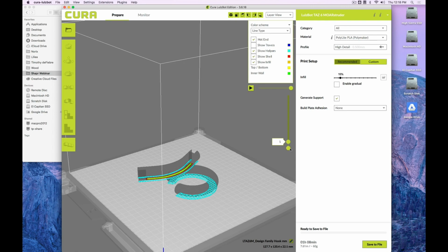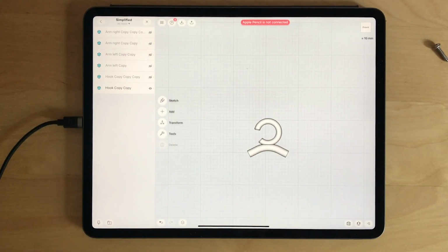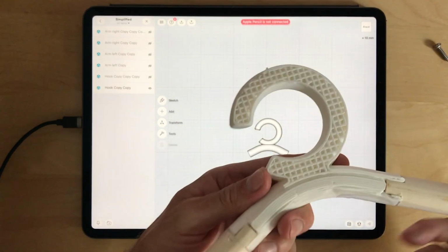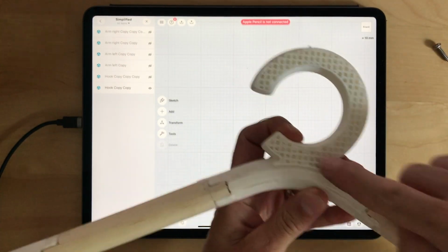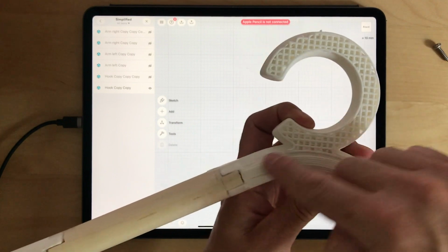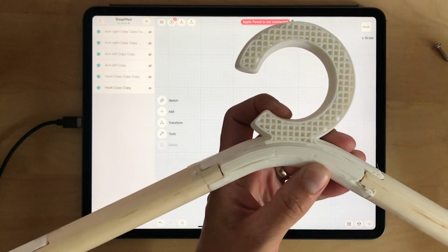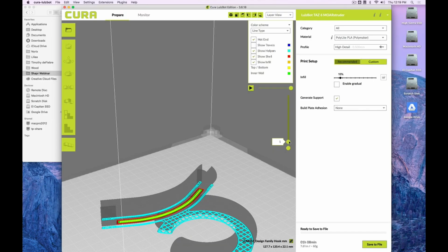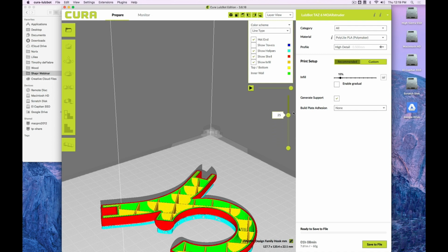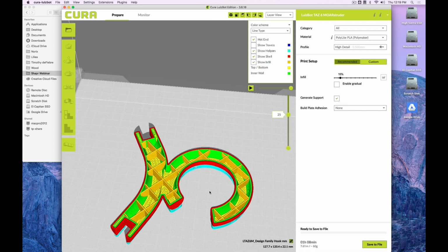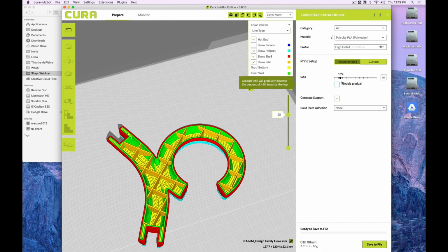When you see that structure, what you see there right now, that is also what you can see now in the camera. There's the gridded part, and there's that little bit of support left and right. And even in the first layer, if I zoom in, you see the model there starts already. What's red is actually the outside shell. And even inside, you see the yellow, that is actually a structure the 3D printing software creates for you to strengthen it out. That's called the infill.